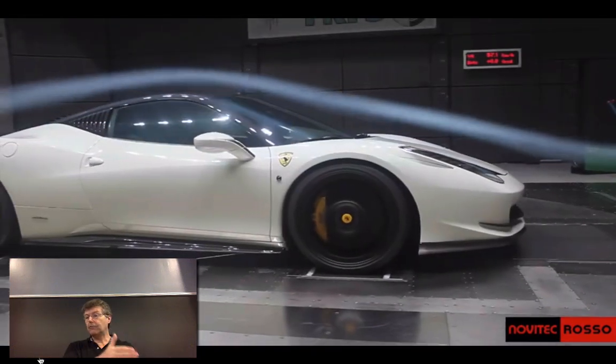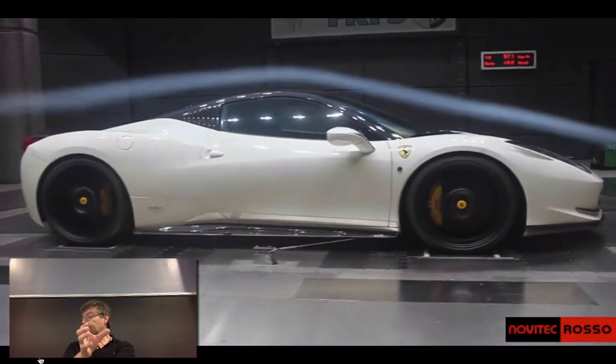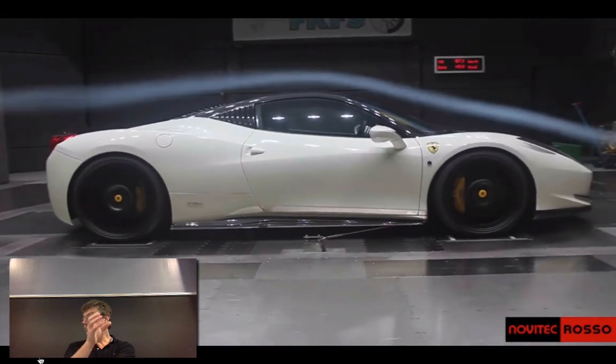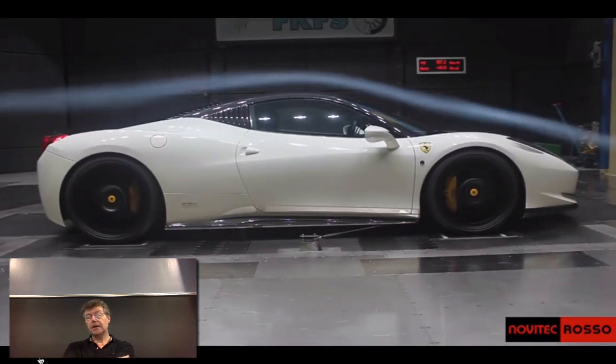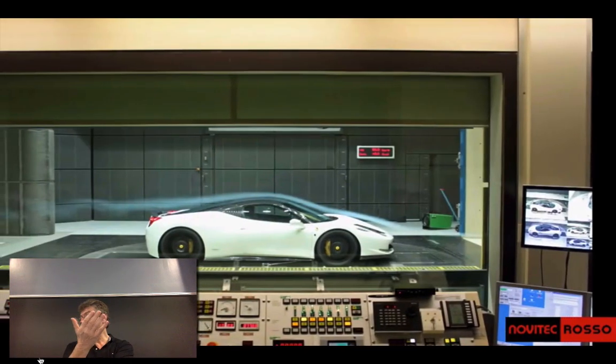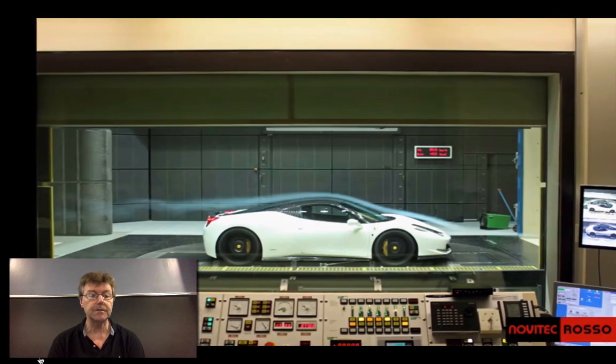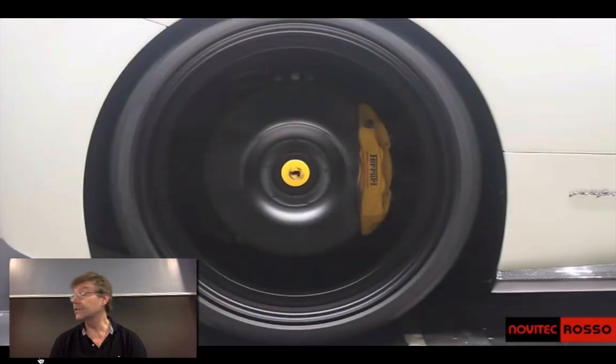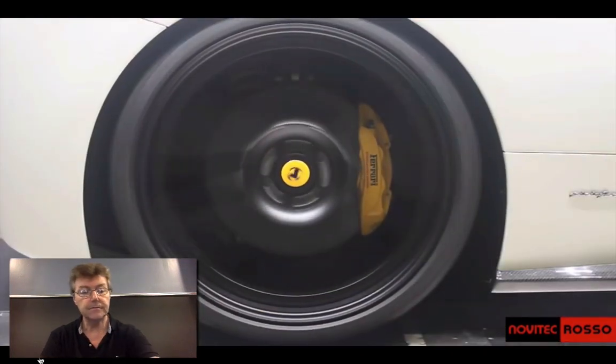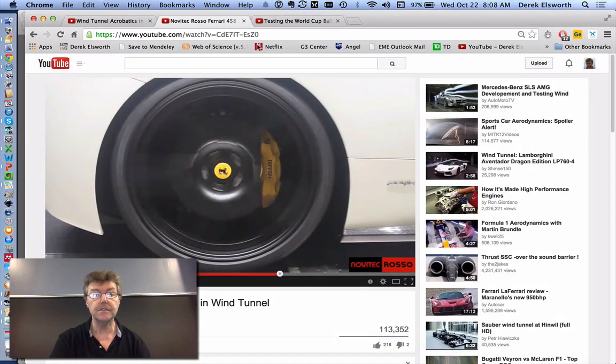And if you know that force at that particular velocity, you can figure out exactly what portion of the power, the product of force times velocity, you'd have to use to power that car just to get over air drag. And so you could see what proportion of your energy consumption, if you like, fuel consumption, would go as a result of that. So that's a typical example of what we might be interested in.